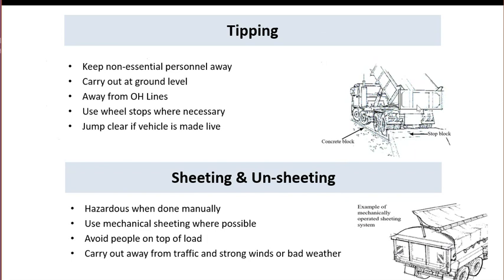And then there is tipping. When they have tipping, they should have a stop block, and it must go on a concrete block and away from the overhead lines. And for sheeting and non-sheeting, it is very important that it is carried out away from traffic, and strong wind or bad weather, to protect the things that they are carrying.